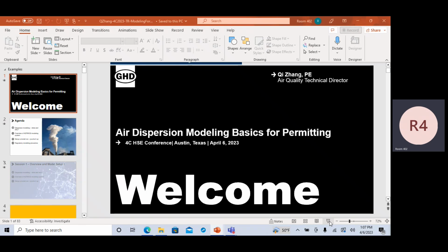And we also have a dynamic simulation, the Lagrangian puff model. We usually use CALPUFF. By the way, I forgot to mention, the Gaussian air models, AERMOD and AERSCREEN3, are all Gaussian models. The Lagrangian model simulates a puff of air starting from the origin.